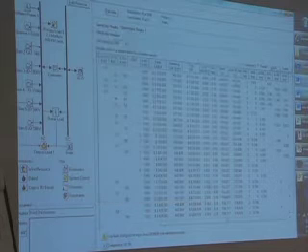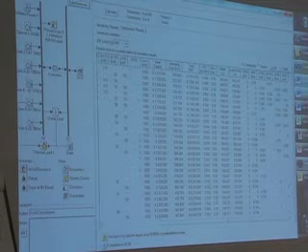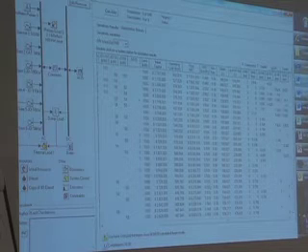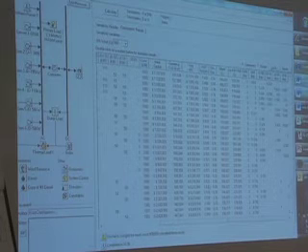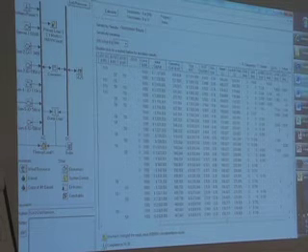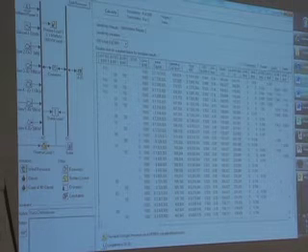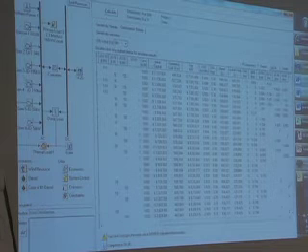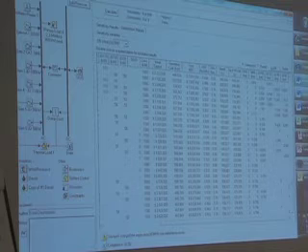So what Core did, which is really handy, we only have one fuel, but we want to be able to easily track how much of that fuel is going to the boiler and how much of it's going to the generators. So Core created a new fuel. It's identical. It just has a different label, and therefore we can see this is the boiler fuel and this is the generator fuel. So 275,000 liters a year of generator fuel and 188,000 liters a year of boiler fuel.